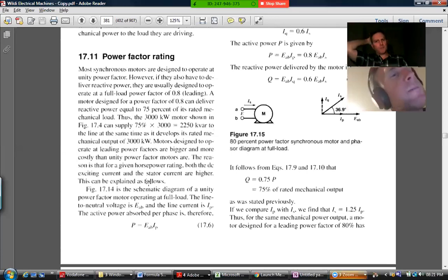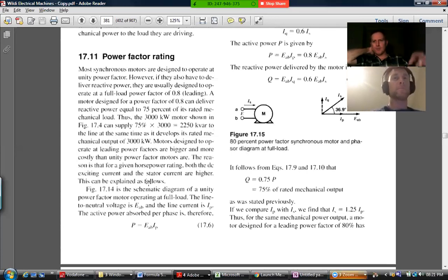So if you've got a big factory, you can actually do some power factor correction by having a synchronous motor in there. Because if you overexcite the rotor purposefully, it'll force reactive power into the grid. So some factories do that. Instead of having a whole big bunch of capacitor banks to try and correct the power factor, if they do have synchronous machines available, especially big ones, they can purposefully choose a level of excitation which overexcites them, which actually forces reactive power into the grid.